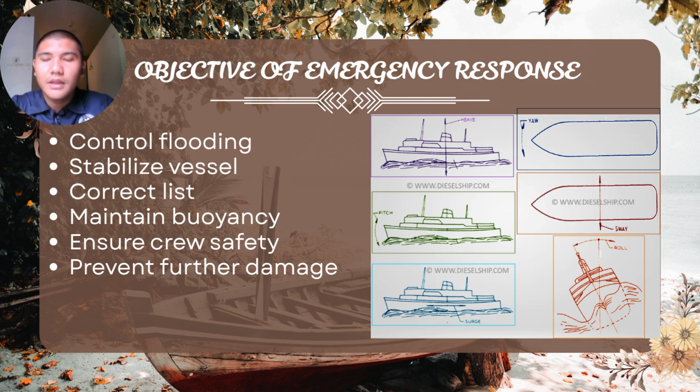Objective of emergency response. The main objectives of the emergency response are to control flooding and then stabilize the vessel, correct the list, maintain buoyancy, ensure crew safety, and prevent further structural damage.